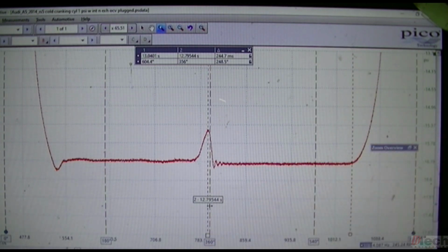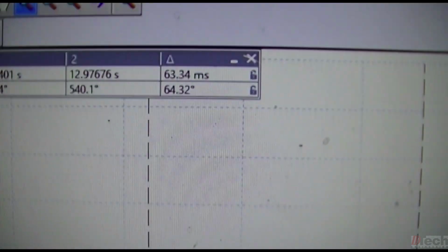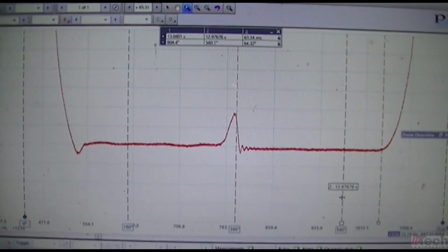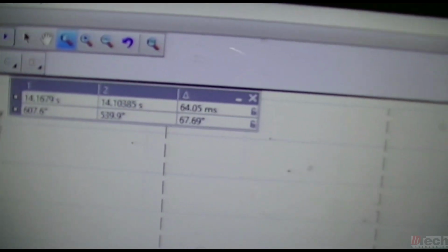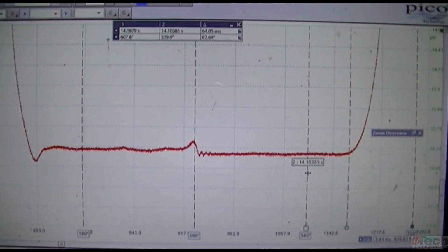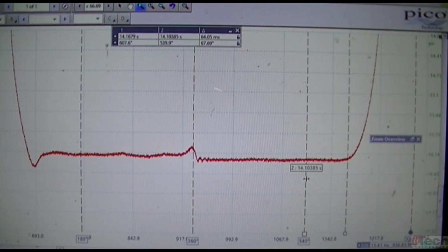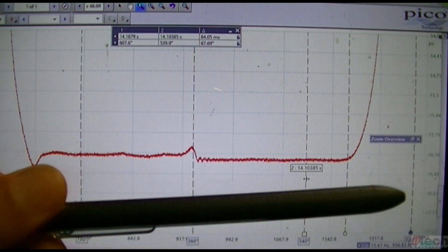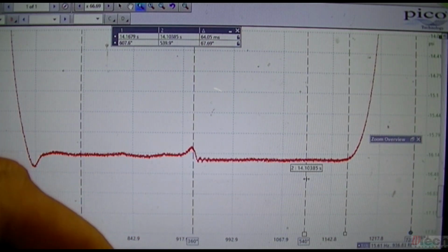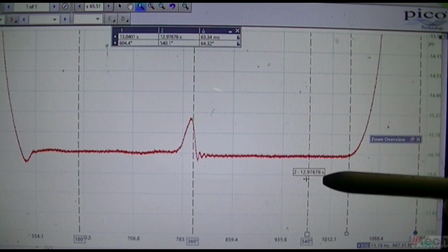The intake valve closing, bank to bank, we can compare. This one's showing up at about 64, and this one at about 67. So bank 2 looks like it is again more towards the right, so bank 1 is happening earlier.